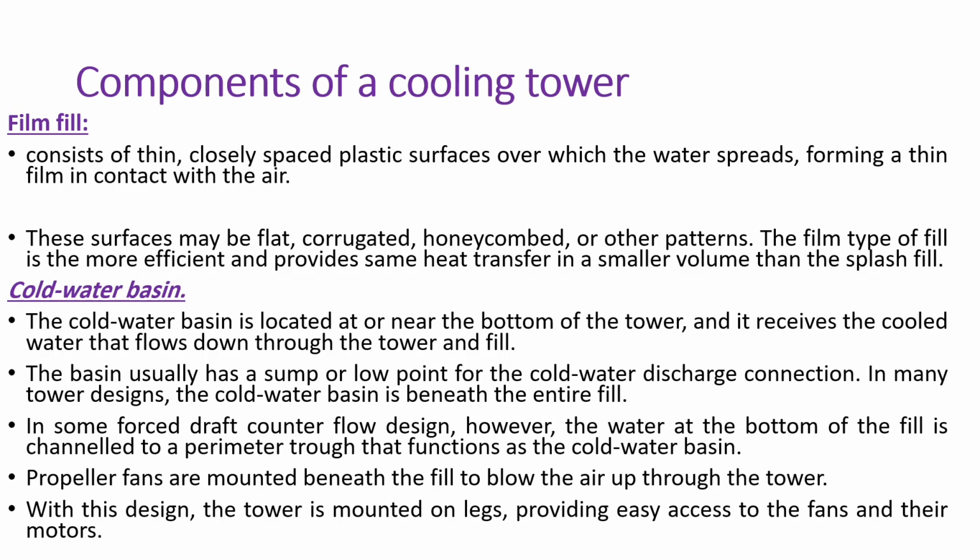Film fill consists of thin, closely spaced plastic surfaces over which the water spreads, forming a thin film in contact with the air. From its name, it is film fill. It has a thin film. So in film fill, water spreads as thin films over surfaces. And film fill is more efficient as it requires less space.